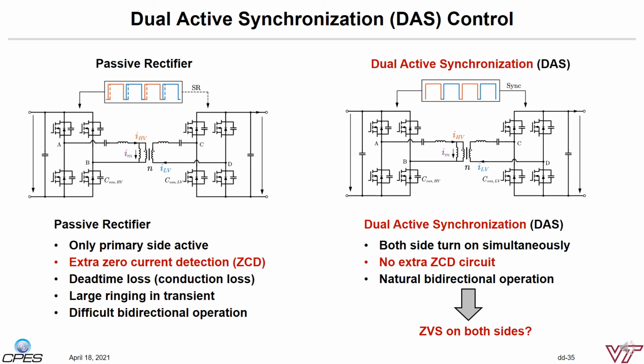There are two ways to control the CLC resonant converter. The first way, and also the traditional way, is to operate it as an LLC converter. Therefore, the receiving side is treated as synchronous rectifiers. It's simple, but an additional DC-DC circuit is needed, and it's hard to operate in bidirectional mode, as the control needs to swap the gating functions when the power flips direction.